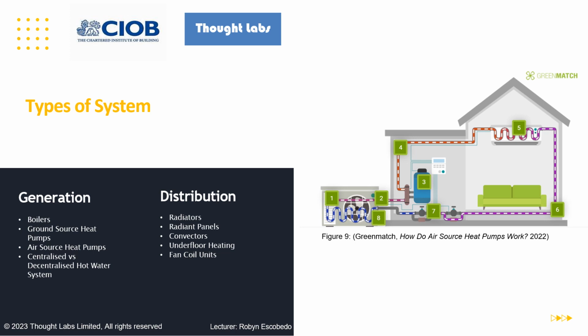This has a coolant flowing through it, so the heat from the air is transferred to the coolant. So the coolant is turned warmer, and as it heats up, it turns into a warm vapor, which passes through a compressor, which is number 3. This compressor increases the temperature and compresses it to a dense vapor, which is number 4. This hot coolant vapor transfers to the indoor units through the internal piping systems. Again, it's showing you as number 4, your hot vapor.